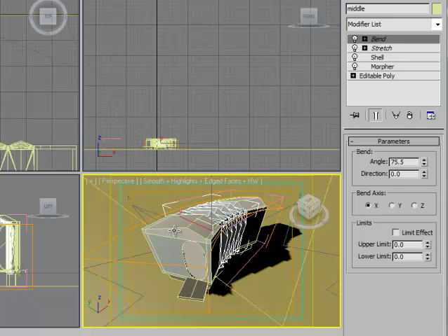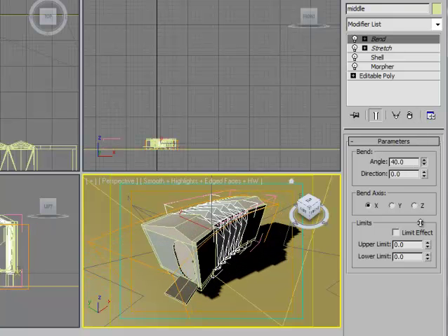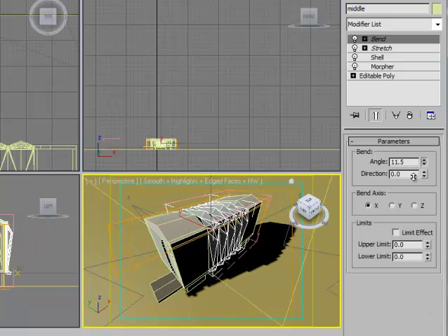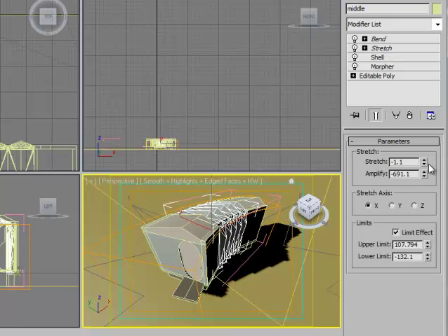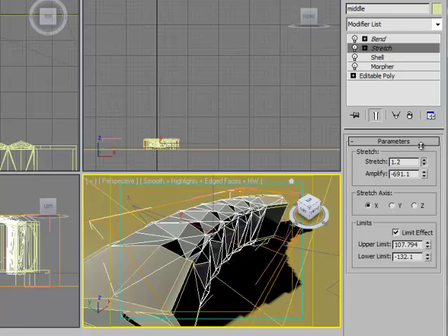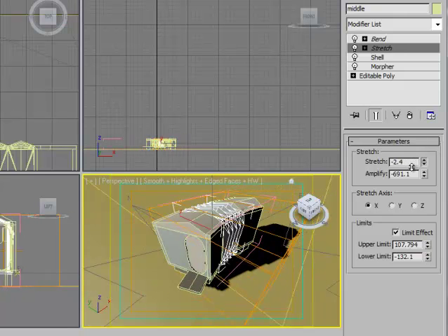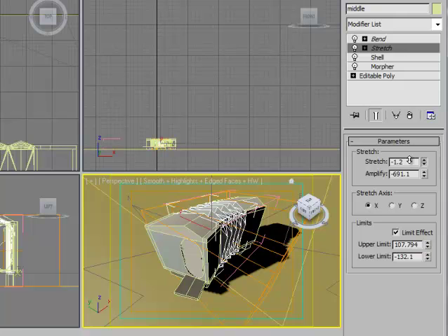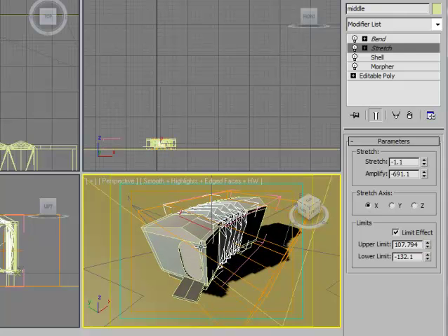the objects simultaneously, such that if we go to use the bend, we can see all three objects are bending together. We can also see that there's a stretch that's applied across all three objects, so that when we use the stretch, all three objects stretch. Looking really carefully, you'll notice that the stretching and bending only occurs over the length of the bellows-like form, so that the solid pieces, the end caps on either side, just like in an accordion, do not bend or stretch or distort in any fashion.